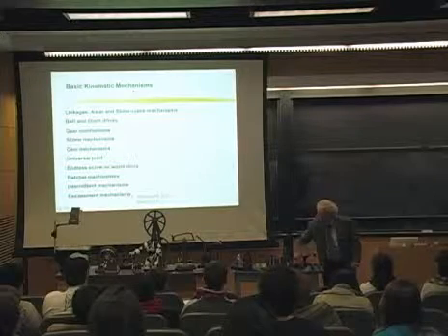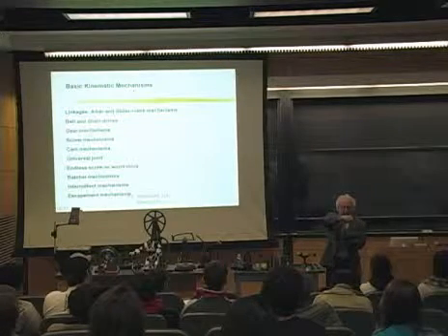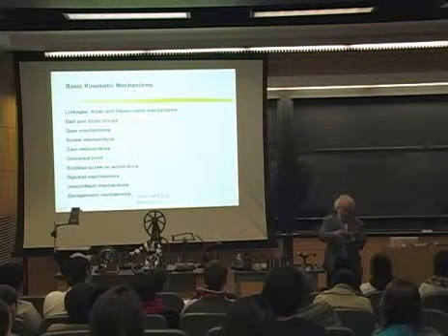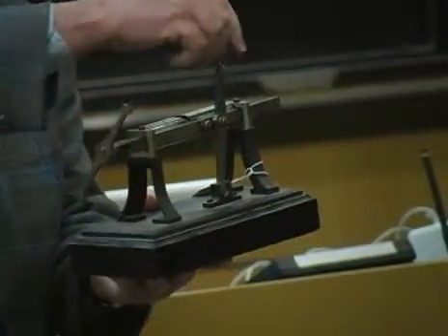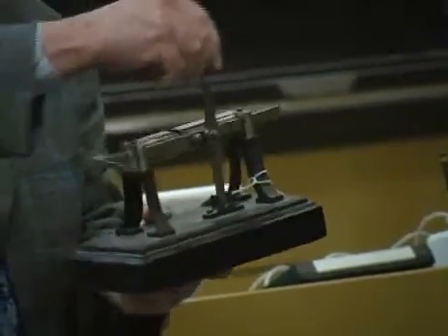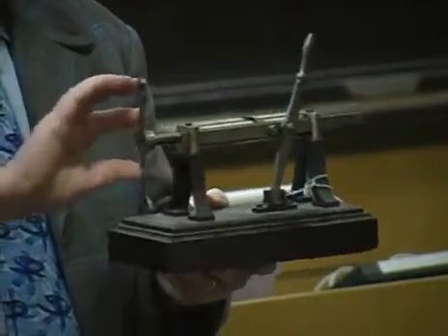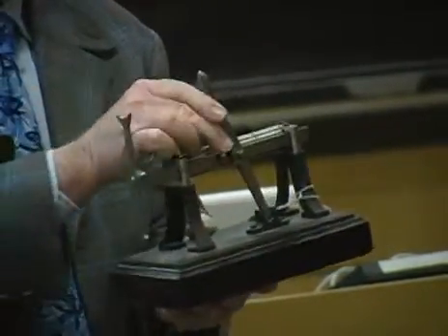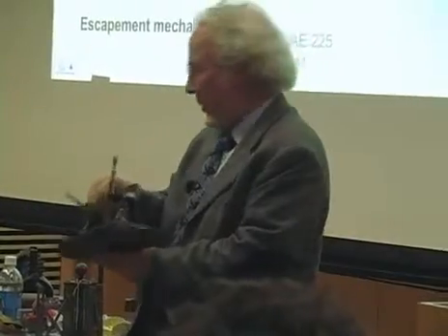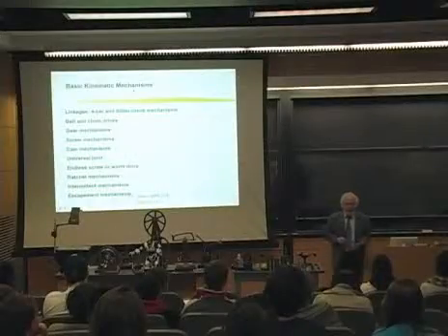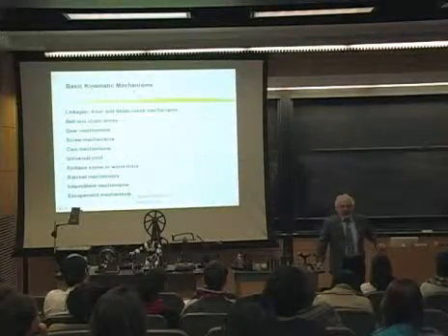Here's a kind of screw mechanism, in which you see there's a screw in this cylinder, and as I turn this, I convert this into rotary motion here, or I can have rotary motion converted to linear motion here. These types of mechanisms are in ball screw devices, in the vertical stabilizer for a jet aircraft.